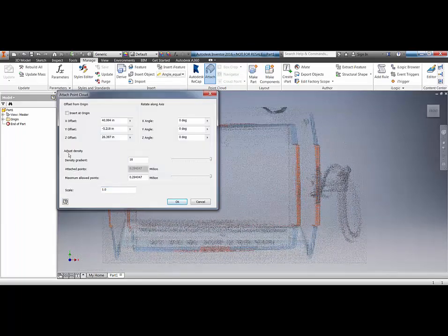Now here we can adjust the density, so how many millions of points we bring in and how dense the point cloud is. Now you will see a difference between bringing in focus data and freestyle data. Specifically, it comes down to volume. With the focus, we're scanning much larger objects, so the point cloud will appear to be denser. On the freestyle, we're scanning typically smaller objects.